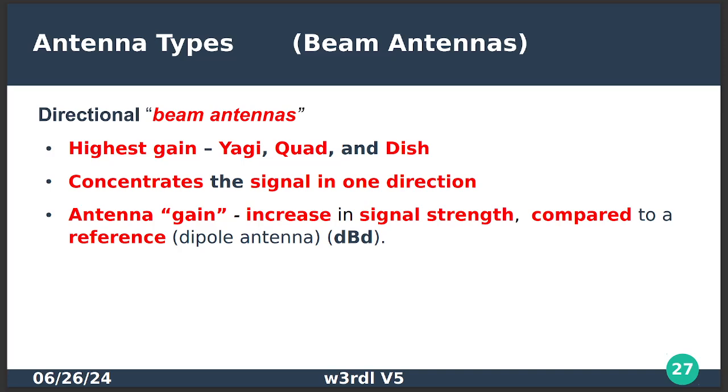And this antenna can be tuned by using this shorting strip right here. You can tune it, you move it back and forth. Well, it's got one there. It doesn't have one on the other hole, but it's got a little set screw right there. You just loosen the set screw and you can slide it back and forth to tune it to your preferred frequency. So, okay, you'll notice that it has a beam and some elements attached to the beam.